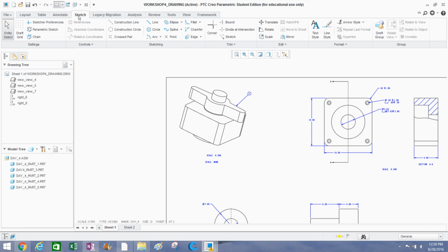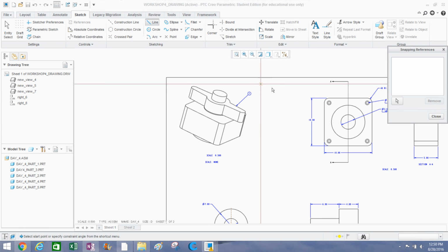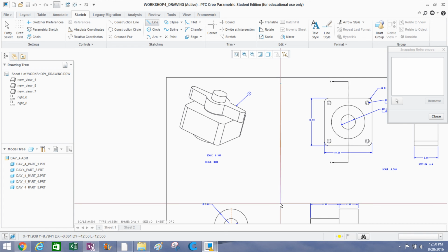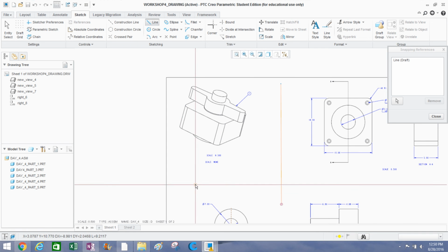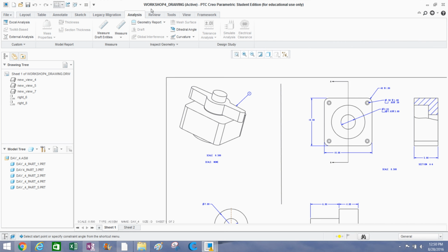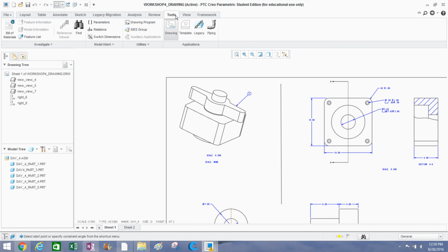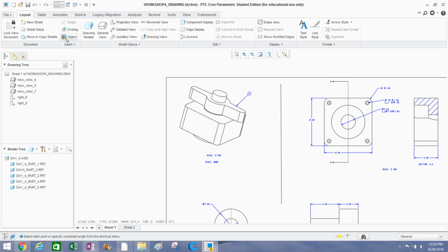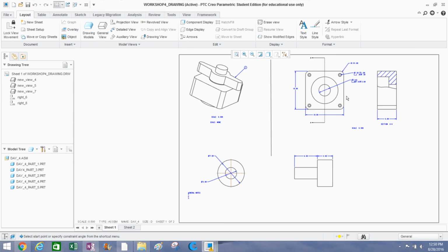If you go under Sketch here, you can actually sketch on the drawings if you want to sketch some kind of dot line to separate something. Come to line and just put a line on the surface of the drawing. Come off the center, click, and now you've got your line. Maybe separate parts and create circles, splines. Here's that hatch I was telling you about, changing the cross hatch over there. All these different options. Under analysis, you can measure a part. Here, view. There's so much here. I'm only scratching the surface. I really am. So we're going to go ahead and drop off here.